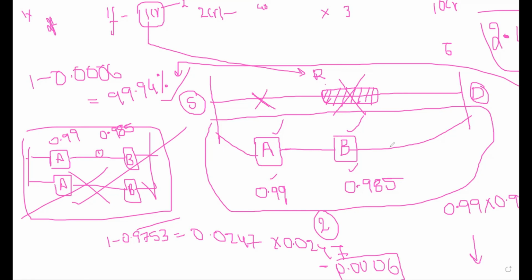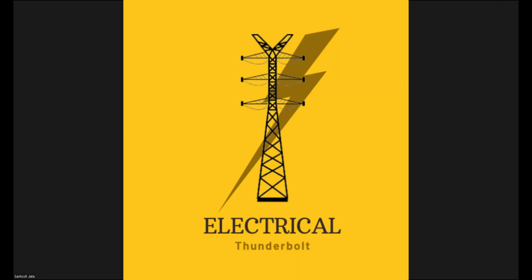In substations, the main factor is tariff. And if you go for industries, it depends upon the plant outage, production outage. Suppose the auxiliary supply is lost, so the cylinders are not manufactured. There is some delay, so you are losing some amount. You have to calculate that. In substations, we calculate with respect to the tariff. Understood? So in industries, reliability also plays a very major factor, very important. In substations it's not mandatory, but in industries it is very, very required.